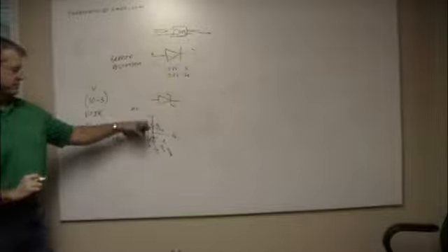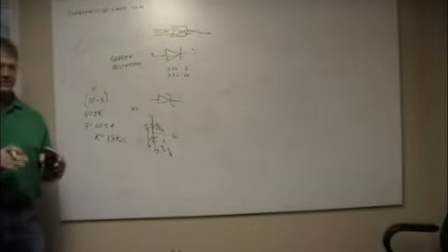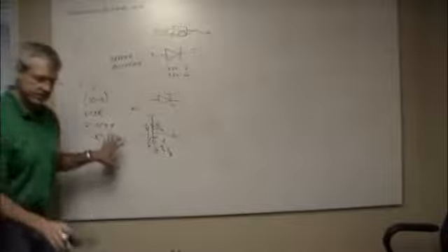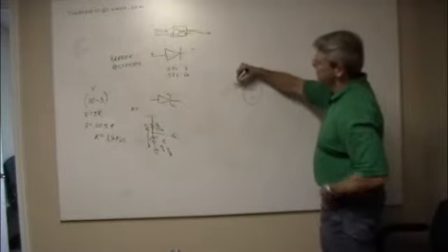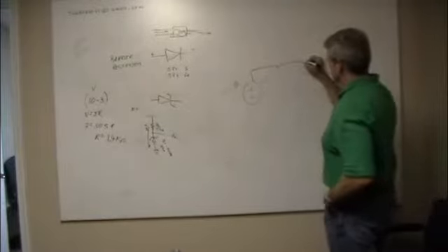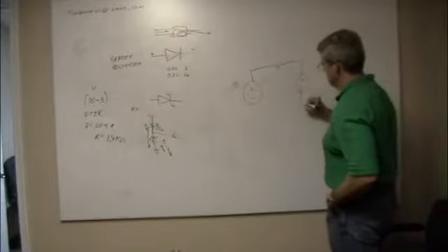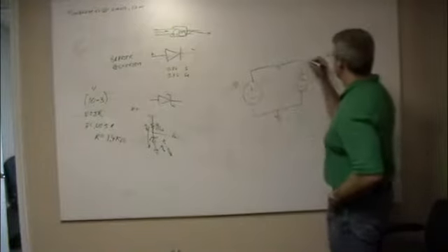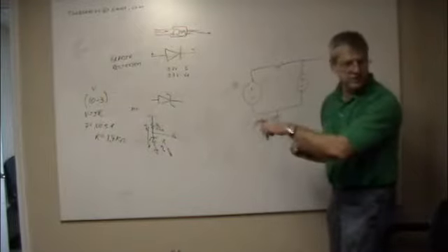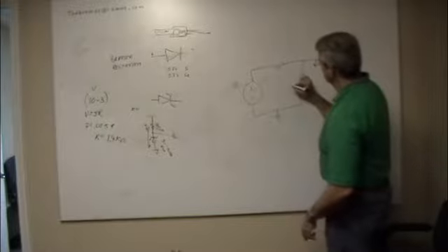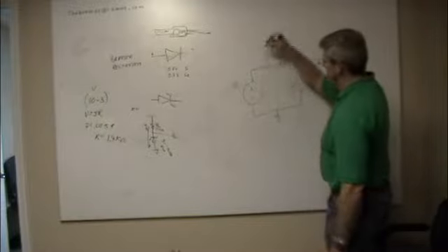And now I've got a 3-volt reference out there. The truth is, as soon as I put a load out there, you're going to change. There's going to be a little bit of current flowing that way, so you're going to do a little bit more math. But this is what I was talking about with the Kirchhoffs a while before, where I have some supply that's a 10-volt supply. I've got my resistor. I have another voltage source here, and I play this game. I know he's not a voltage source, but I treat him as one for this. 3 volts. So again, we do our math.